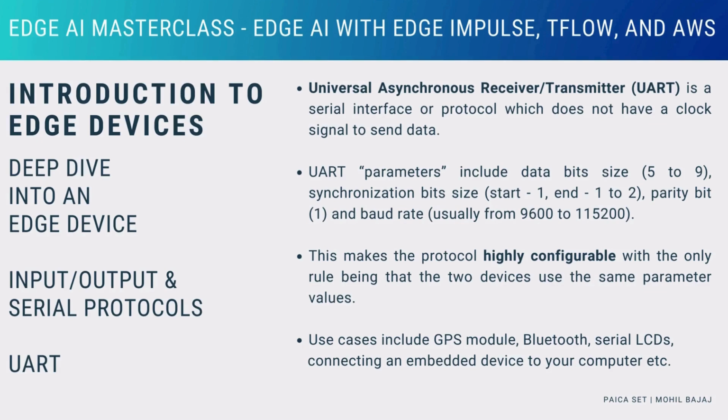So let's dive in. UART, or Universal Asynchronous Receiver Transmitter, is an asynchronous serial communication protocol. This means that, unlike parallel communication, which sends multiple bits at once, UART sends data sequentially, one bit at a time. Also, since the communication is asynchronous, there is no clock to synchronize the data sent and received, and it uses special bits to let the receiver know that data is being sent. We will look into this soon, but let's go over a few terms first.